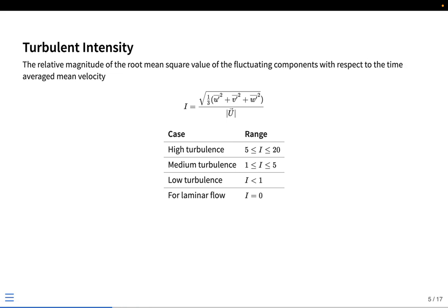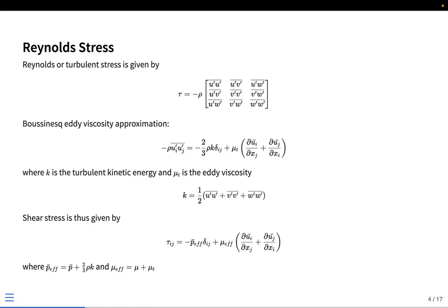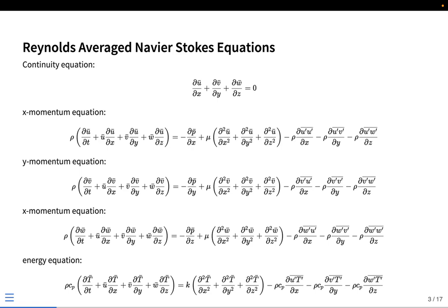And then if, instead of using the integral momentum solution, you want to use CFD or other techniques, then you have to use the differential form. In the differential form, the equations are given by this particular term. Of course, these are unsteady RANS equations, or URANS, but for the usual Reynolds-averaged Navier-Stokes equations, you do not have these unsteady terms. So these terms will actually get cancelled off because we are averaging over time.